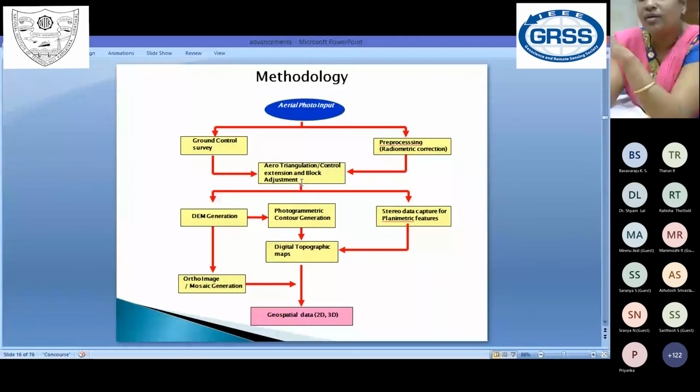And in the case of satellite also, if one image coverage is not sufficient, or because you have the limitation of onboard sensor position as well as attitude, we need to have some precise ground control, and we do the space resection and intersection simultaneously to make it precise to the ground. So that we do in aero triangulation.